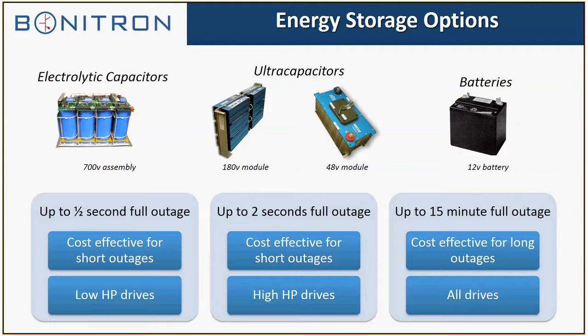And with batteries, we say up to 15 minutes, but I actually quoted 4 hours last week. So time is pretty much unlimited, but when you get up past 15 or even 30 minutes, the cost of the batteries and the weight of shipping and all the logistics issues that go with it, service contracts, battery maintenance, the cost gets pretty extensive as compared to what the same type of issues would be with the ultracap energy storage. There's no service contract with ultracaps. They have a much longer life than batteries, so that's why we try to promote the ultracaps as much as we can. But as I said, 5 seconds right now is the time that we see as being ultracap economical.